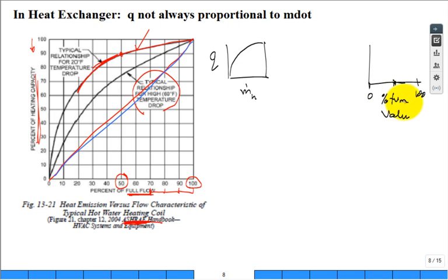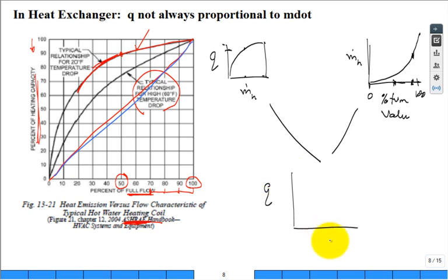Okay, well, if you could get the valve to have the mass flow rate to match such that the hot fluid would do something like this, then as you closed it by 10%, there would be a huge reduction in the mass flow rate. Huge reduction in the mass flow rate would lead to a 10% reduction in the Q. And so you put these two together and you get a better system for control, the valve percent turn or ratio or percent open, 100% open right there. And then you get it to be nice for the controls people.